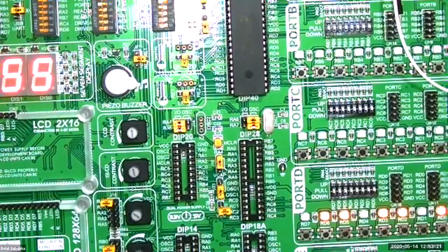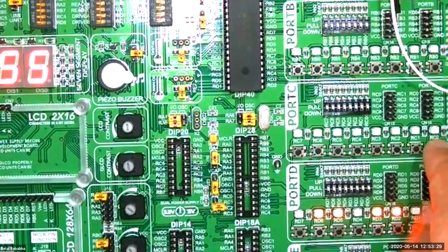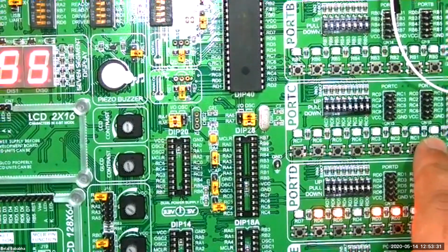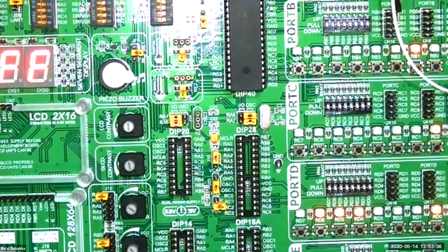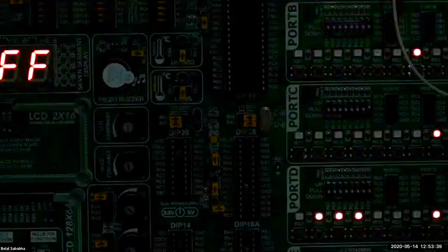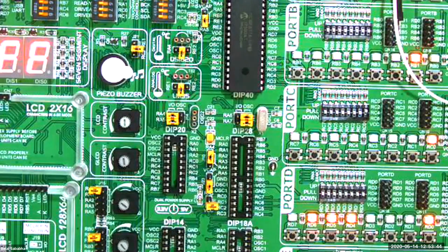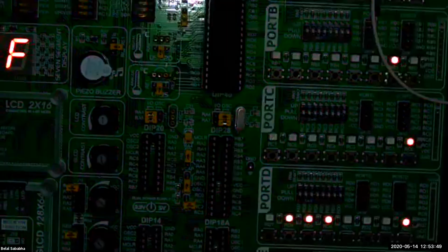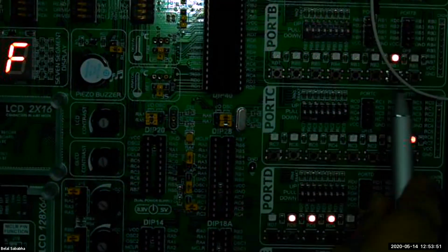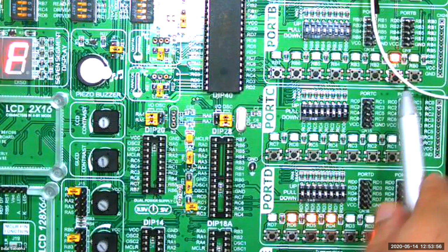S. So I said if I press port C0, I want the motor to run at full speed, right? Full speed. I just want to do the pull up. Now I pressed full speed. See, it is F. The motor is turning in full speed. And if you look at port B, do you see port B? Port B0 is 0, port B1 is 1. And it's moving in one direction.